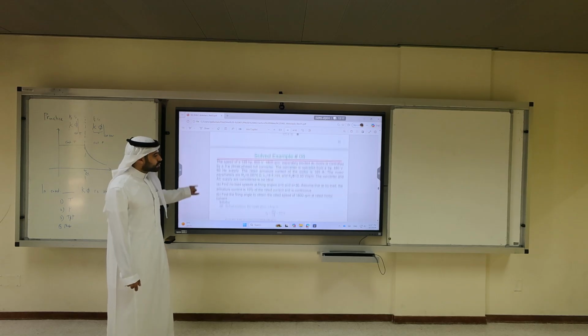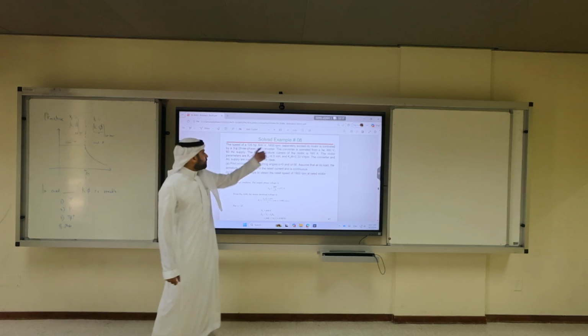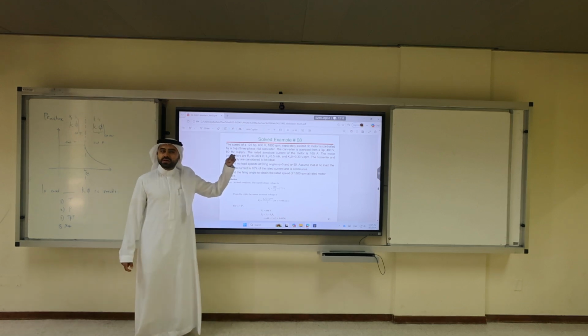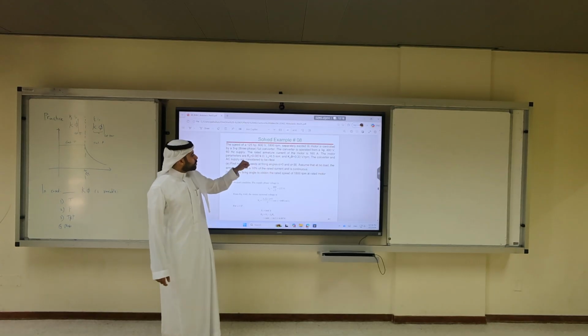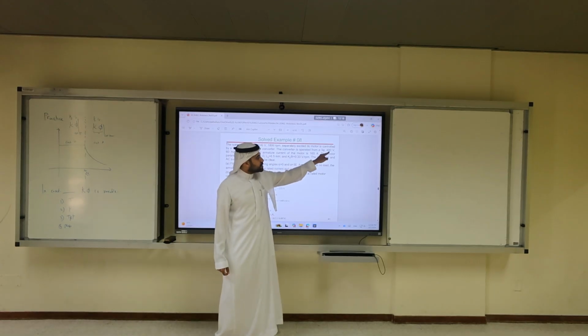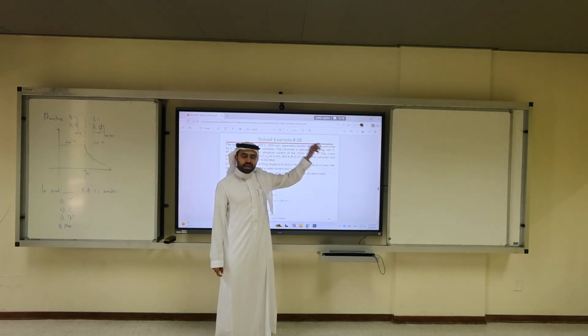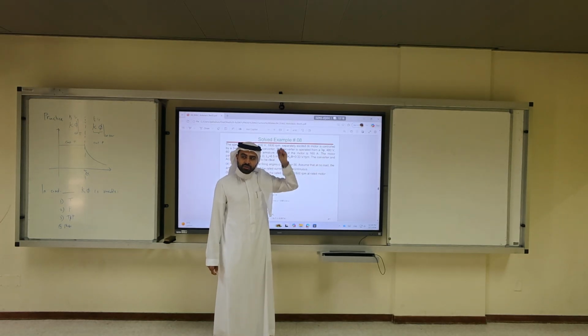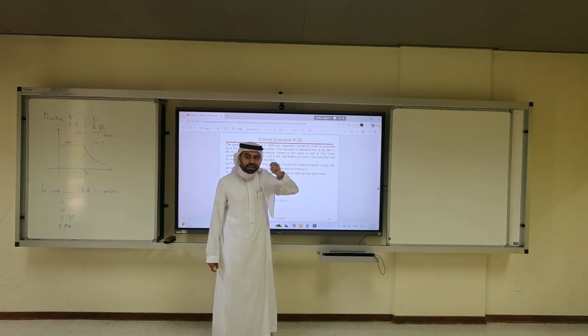The other example is separately excited, but now it's controlled by a three-phase converter. The converter is operated from 480. Is 480 line to line? It is line to line, because in three-phase we love line to line, which is also RMS. In single phase we do not have line to line.